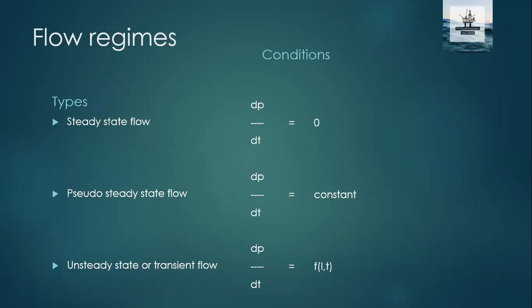10 psi have been reduced. When it comes to T3, 1550 have become 1590, sorry. Why? Because 10 psi out of 1600 will be 1590. So from 1590, it became 1580. At each time level, a 10 psi reduction of pressure is observed at one particular location. Let us take that location to be xi.